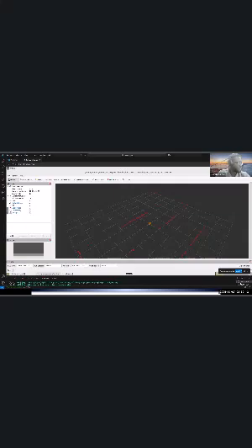For the image topic, I'll show you something. If I click on add, you see different topics are available by topic. There's IMU, there's depth cloud, there's camera, there's joint, there's pose, there's LiDAR. Can you see what we said about LiDAR? Slash scan, that's the topic. So slash scan is the topic, right? The LiDAR is there.